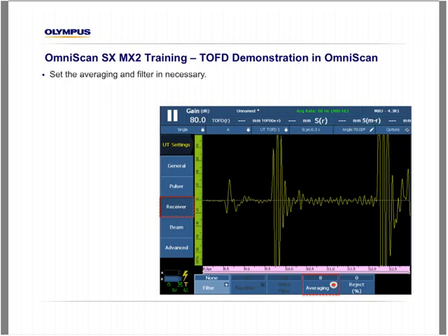Averaging is selected based on what works best. The averaging factor will create an additional A scan for each factor of 8 in this example, and it will sum all of them together, subtract the difference, and reduce the noise that we see as compared to the relative signals. This averaging, historically for TOFD, is most useful for use of long cables and accessories and extension boxes.